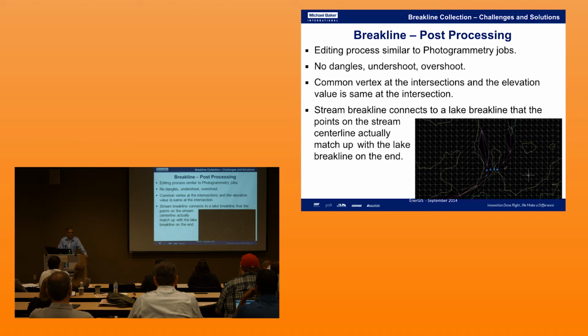So you make sure that all the information you capture in post-processing is properly translated. At the same time, you make sure that standard GIS-related checks like no dangles, no undershoot, and no overshoot are met, so that the contours are clean files for the end user. These are some of the post-processing challenges in meeting different client requirements when moving data from one platform to another.